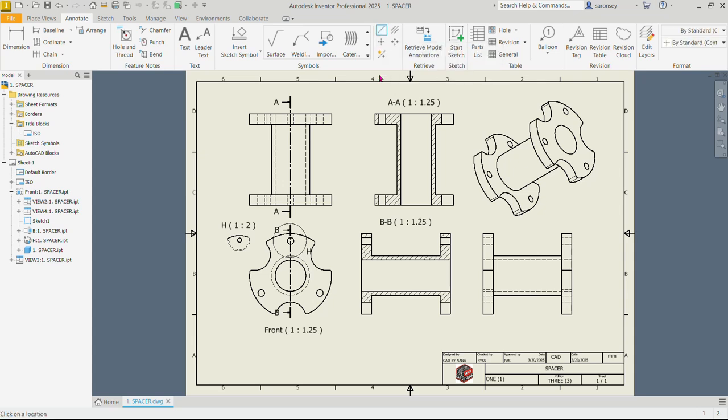The first one is the center line. If you want to put a center line anywhere, you just click on that. Now let's locate a point here on this line. There we go. Also another point here. There we have it. You can now click to place. Let's do same here from this point also to this point, and we click again to place. Now if you also have some holes, then we can use this option center mark, so we know the centers of those holes. Just click on that, locate the hole and click. Would also do same for this and that one. We see those little plus signs in there.